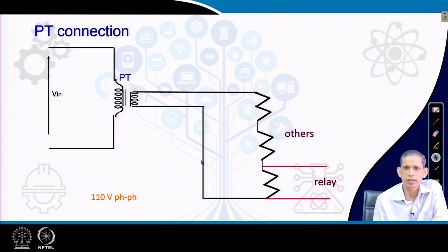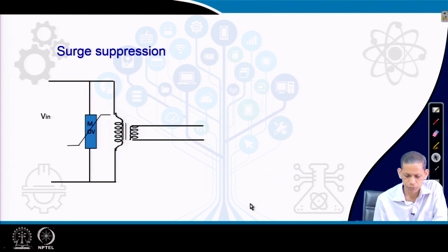So, that has to be considered, again should be downscaled to a suitable value compatible to the relay, and therefore a simple way is a potential divider connection or any other suitable mechanism. As part of the relay specification, the corresponding voltage compatible to the relay should be addressed in this perspective.